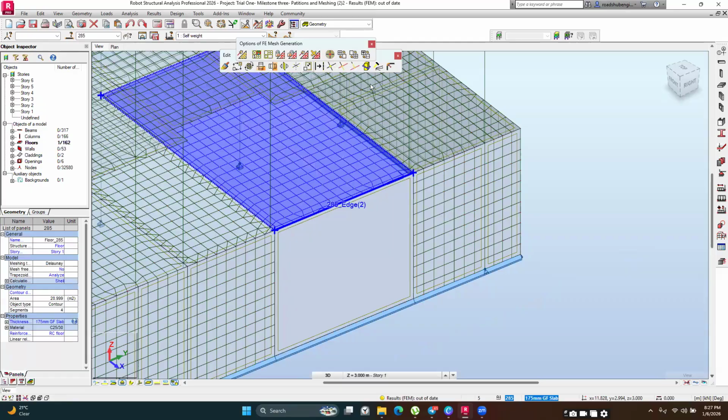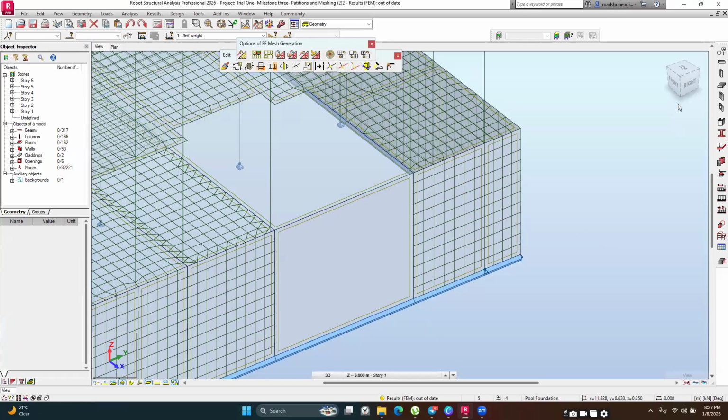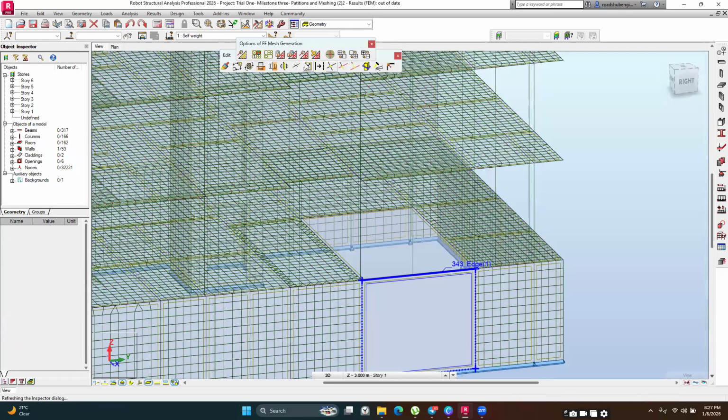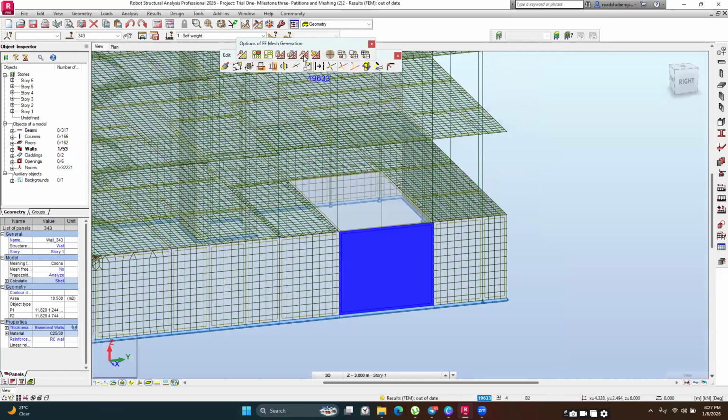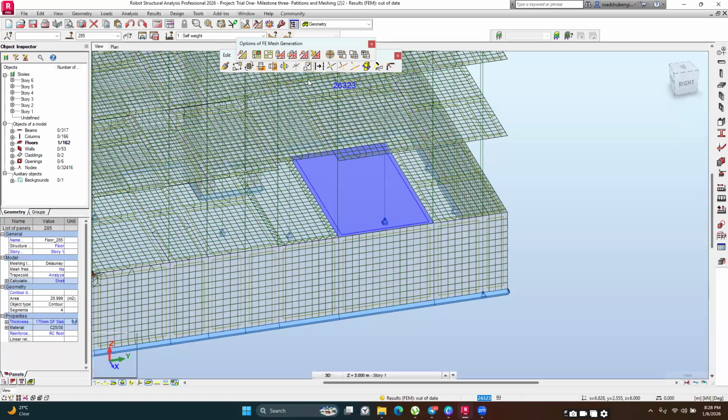Then select this one and delete the meshing for that particular panel only. And then once you do that, select the panel and mesh it. Use the local mesh generator for it. Do it panel by panel so that you try avoiding getting that error.